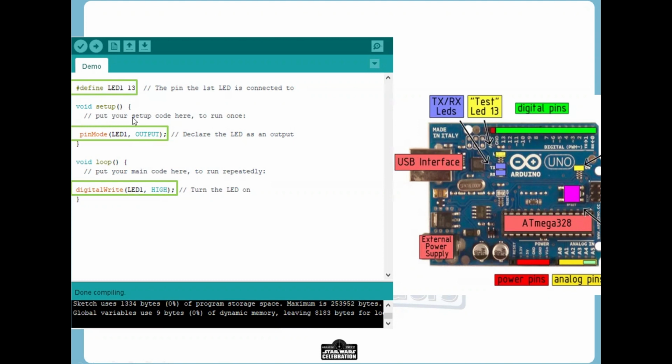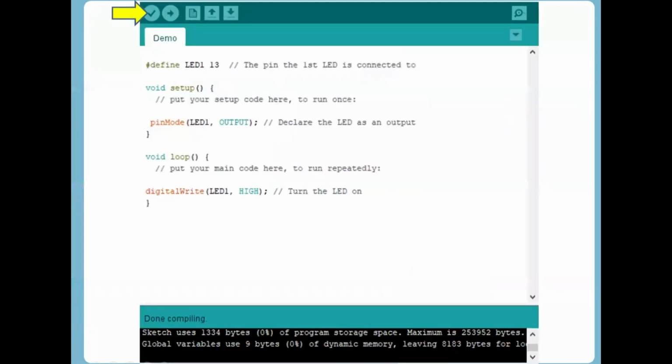Once we type in all these, we put the little semicolon at the very end of the code. We now have 3 new lines in here. So we go in here, click, hit enter, type these in. Once we have done that, and we've got the structure ready and we've defined these variables, we now click on the very top up here, our compile. See that up here? Click on the very top there to compile.